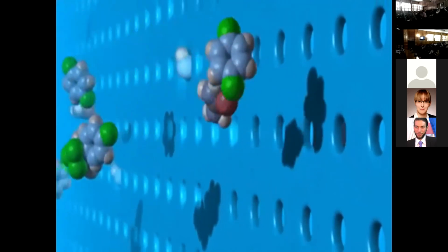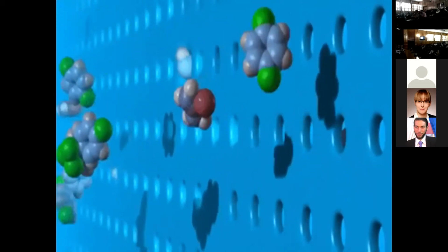So our target is decreasing the problems of RO or nanofiltration membranes for desalination of water having a high concentration of iron and manganese, by using a pre-treatment adsorption process, not ion exchange only, but adsorption, having all the mechanisms take place with higher affinity and higher capacity, to overcome the problems that take place for the membrane and increase its lifetime during its work with this type of water.